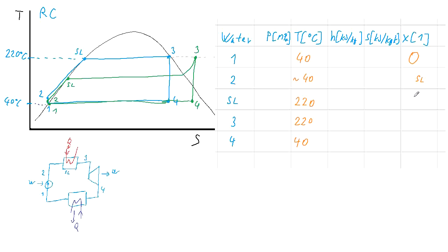At the point of saturated liquid, let's call it like this. Now the steam quality at the point 1 is 0 because it's on the point of saturated liquid. Then at the point 2 it's subcooled liquid, so it doesn't have a value. Point 3 already says saturated liquid, so we get at the higher pressure back to steam quality of 0. And at the end of evaporation, point 3, the steam quality is 1.